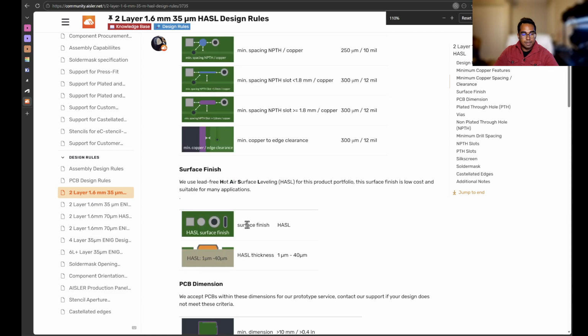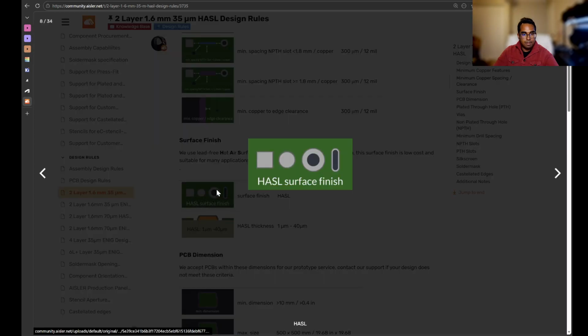The via is structured like this little circle that they show here. Let me see if I can find a bigger image right here. It's structured as this circle, which is just a hole drilled straight through the board with a copper ring, or a metal ring, that lines the inside of that tunnel, basically forming a complete path for electricity to flow through the hole in the board.